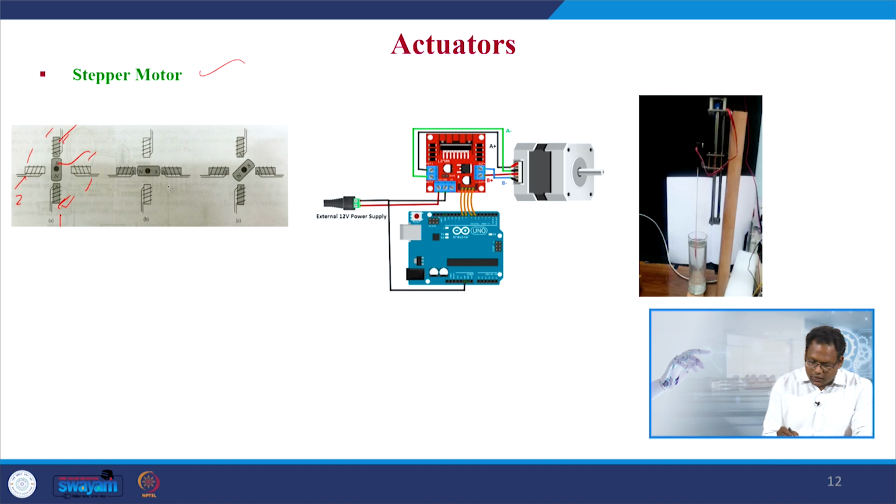When the second stator winding is excited and keeping the stator windings at 1 off, we can see that the rotor is turning 90 degree from the initial case, so that it is now aligning to the excited stator set 2 windings.